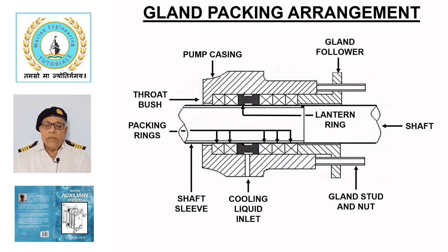Gland packing is comparatively simple and cheaper arrangement than mechanical seal, but it is not capable of arresting complete leakage. Removal of the gland packing can be done without dismantling the pump unless the shaft sleeve is badly worn out and requires its machining or renewal.